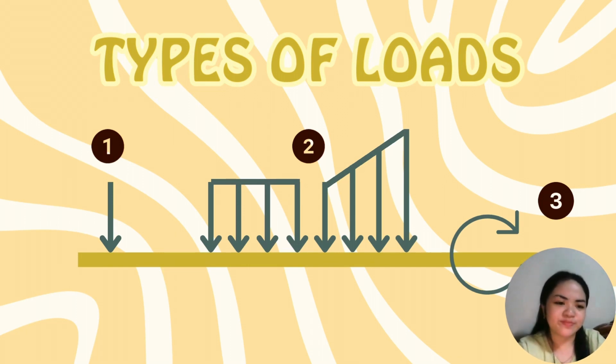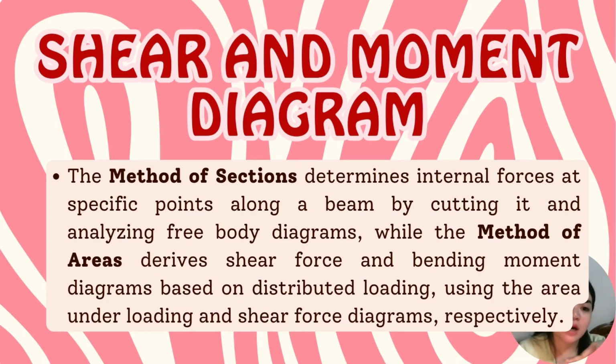So, we now proceed on the shear and moment diagram. Paano tayo makakasolve ng reactions from the different supports? So, for method of sections, from the name itself, section. So, it determines internal forces at specific points along a beam by cutting it or sectioning it by segment and analyzing free body diagrams.